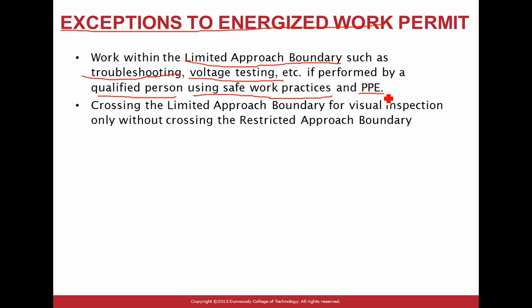So you're not torquing a gear or a circuit breaker. All you're doing is troubleshooting and measuring. You're not working, which means, guys, you take all your 120 control circuits and start taking them apart, untorquing and retorquing them. Now that's work. Testing for voltages, or troubleshooting and pushing buttons, you don't have to have an energized work permit. But I believe that you guys at 3M have to go through the hazard review record to do any type of work, because you have a lot of hazards too.